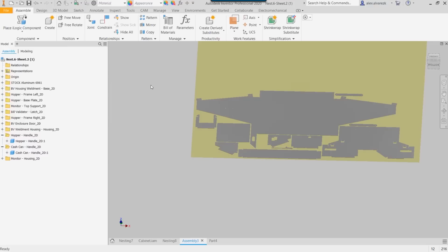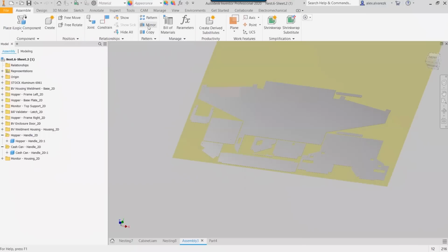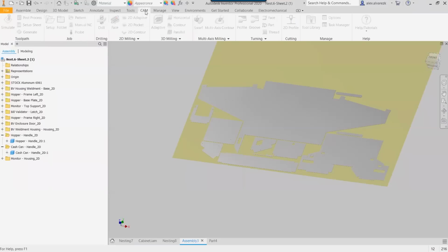And again, that's going to come down to what software you have available. So if you have something that's embedded into your design software, then great, go ahead and use that. But often, another workflow is, okay, we're going to create the nest, and now we're going to generate a DXF file, and then just let our laser or plasma machine take care of that. But in this case, I do want to highlight what the steps are to generating toolpath for this.